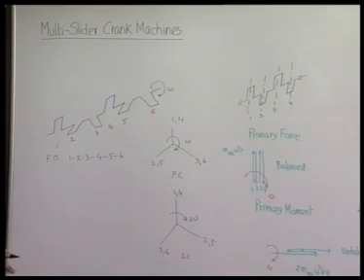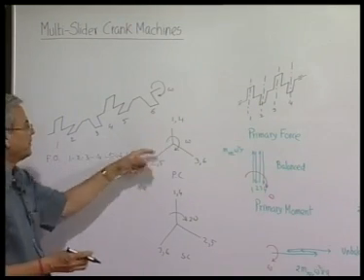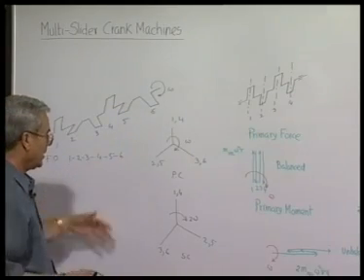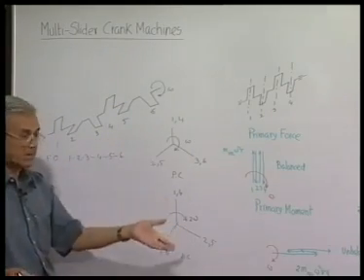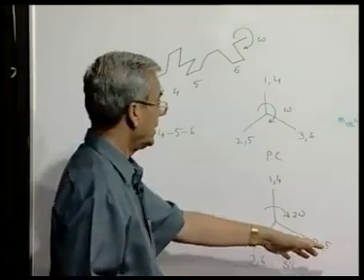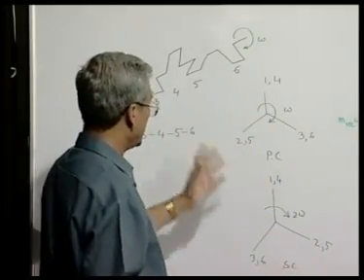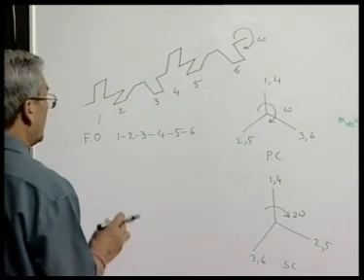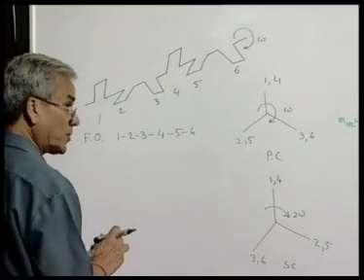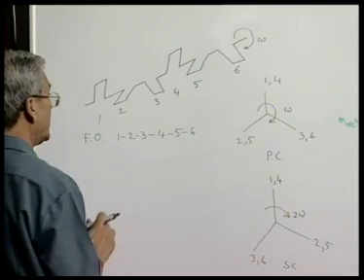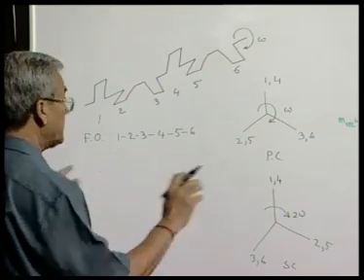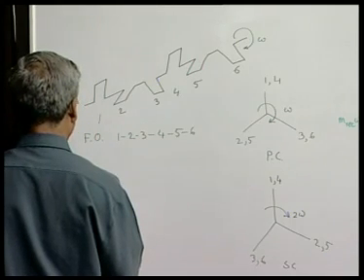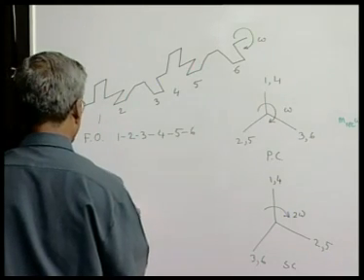So, you can see that if we place masses at the crank pins, the primary forces will all balance because they are symmetrically placed. Secondary forces will be all balanced as they are also symmetrically placed, but primary moments and secondary moments may not be balanced. To achieve both primary and secondary force balance, to achieve primary and secondary moment balance, complete balance up to secondary, we have to take crankshafts which are symmetrical like this.